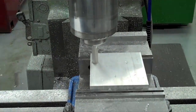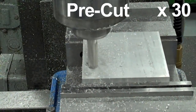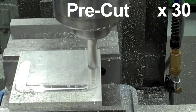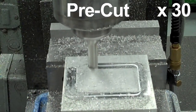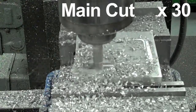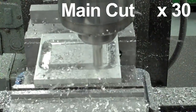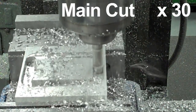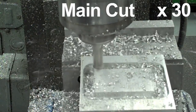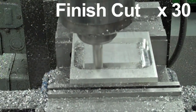While the ProtoTRAK is running, it's a good idea to add cutting fluid or oil to the part. This will keep the part cool and will reduce wear and tear on the tool. Keep the cutter clear of chips and debris with the air blower. If at any time you need to stop the program, just press Stop on the ProtoTRAK or tap the hand clicker. Be sure to stop the program and clear the tool from the workpiece before you stop the spindle.